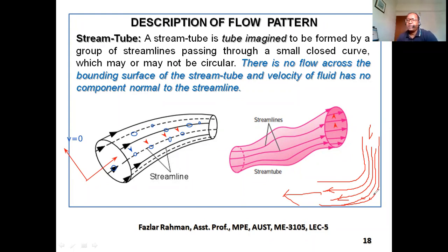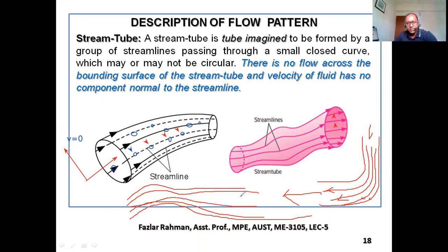And this one, you can give the direction in the software, and it will show you the streamline or flow pattern. For example, you have this kind of flow right over here. You see the flow will go like that. The space between the streamlines right over here is high because it is expanding. But still, the software will calculate that there is no velocity perpendicular to the streamline. That means a fluid particle, say one particle over here, in the next moment will not go in another direction because the y component is 0. Its velocity will always be along the streamline.